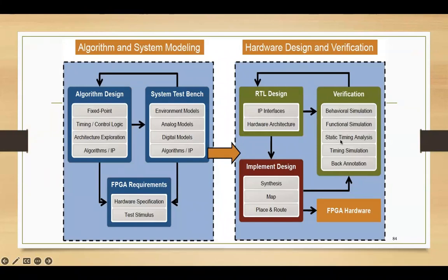Remember, we spoke about the clock skew, right? So timing analysis is done, timing simulation, back annotation. We again get the extracted value. For example, GDS2. You'll be learning more about this GDS2 file once you take up your CMOS laboratories, right? Where I'll be showing exclusively how this back annotation can be done.